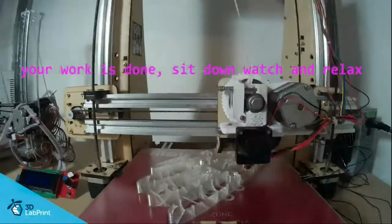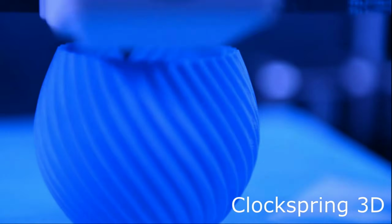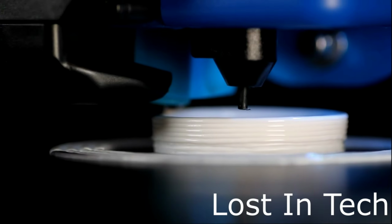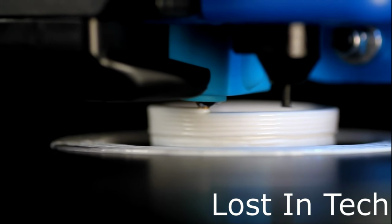One common aspect of these 3D printed plane designs is that they are designed to use a specific method of FDM 3D printing called spiral vase. Spiral vase printing is done by taking a closed section shape and spiraling the nozzle of a 3D printer around in loops until the part is done.